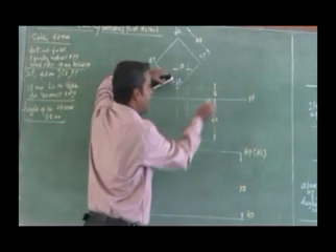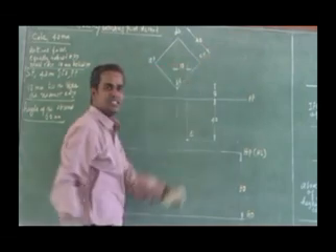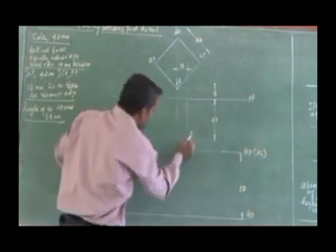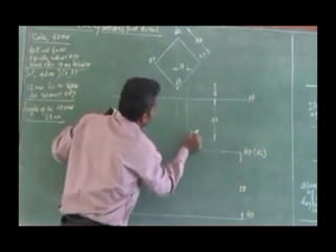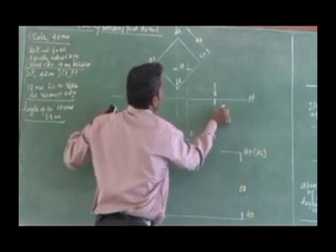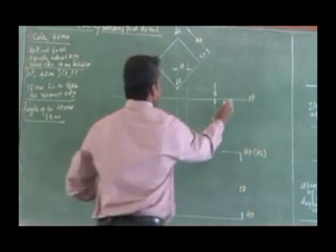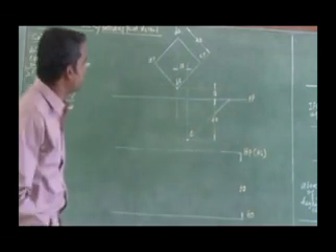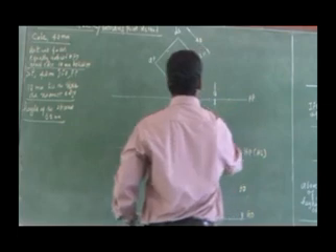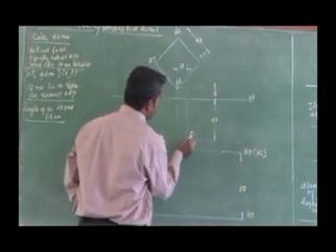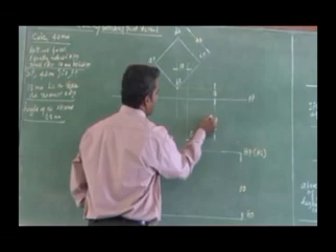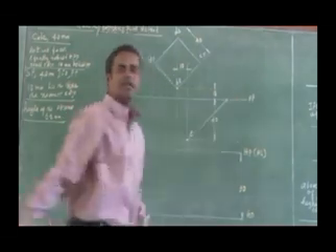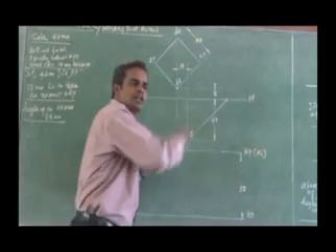Now, to get that vanishing point, see here, from the station point in the top view, you draw a line parallel to one face which is inclined to the picture plane. Which face? That is the BQCR face. Parallel to that, I am drawing a parallel line. It will meet my picture plane. Which side am I drawing the parallel line?